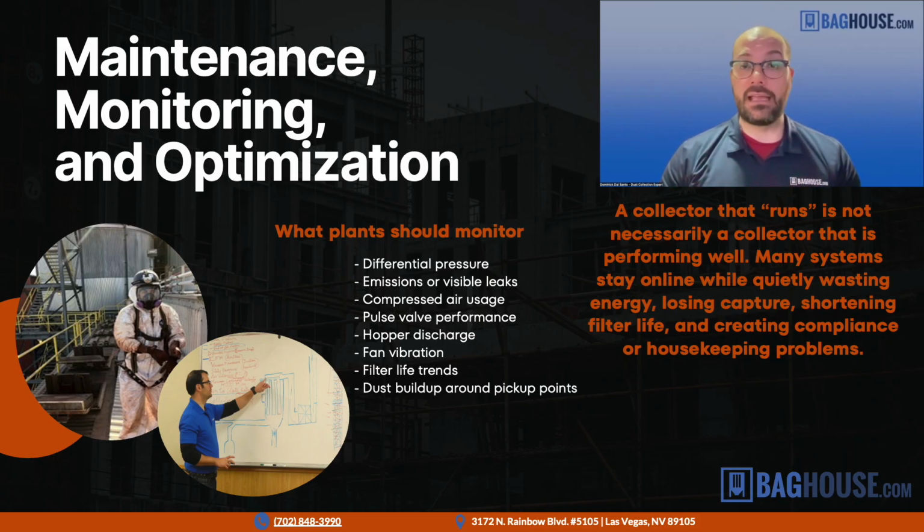This might mean cleaning out the gauges, cleaning out the lines, either weekly or bi-weekly, or installing a device that automatically purges the lines and keeps them clear and clean. But if we don't have that information, we can't make any intelligent decisions about maintenance and operation. So we have to monitor it many times as well.